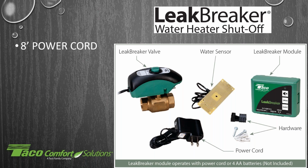The sensor, like I said, already has 10 feet of wire, but you can extend that wire if you want to. If you're going to the water heater right below, you don't need more than what's there. But we can also start adding multiple sensors. You might think, why would I need multiple sensors on a water heater? Well, the original design was for a water heater shutoff valve, but we can also use this as a main whole house shutoff. So as your cold water supply comes in from the street or from your well, you can drop this valve in first. Now we can run multiple sensors.